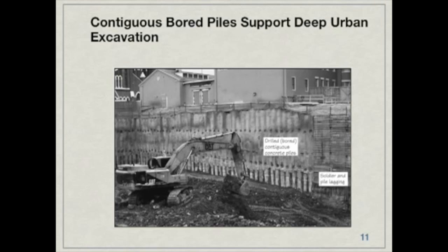Also, if you take a look at the lower portion of those contiguous piles, you can see that they've been shotcreted. By shotcreting the lower portion, what you do is you reduce the water percolation that can come through the cut face of the earth.